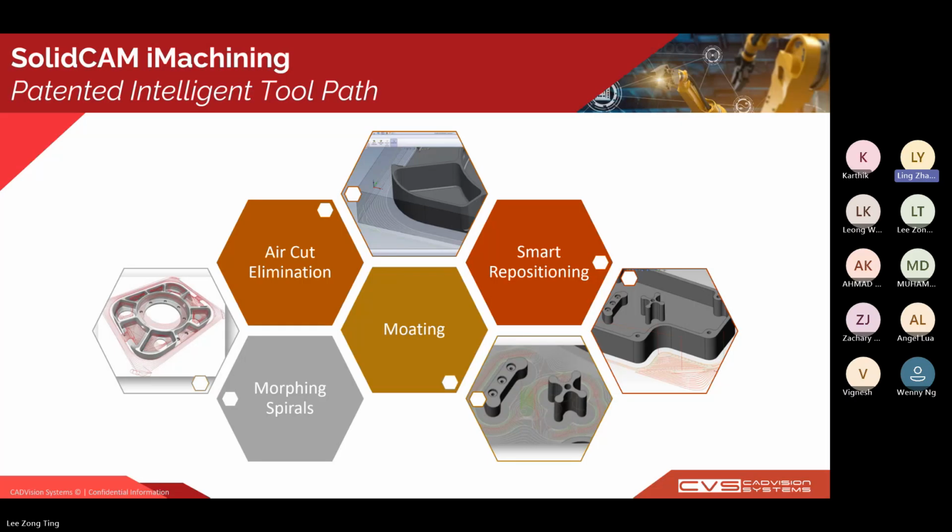So if it has two circular movements, in between there is some filleted radius. Basically, the cutting movement of the tool will be conforming to this geometry rather than the old-fashioned racetrack toolpath. And second, a good advancement under this iMachining toolpath is molding.